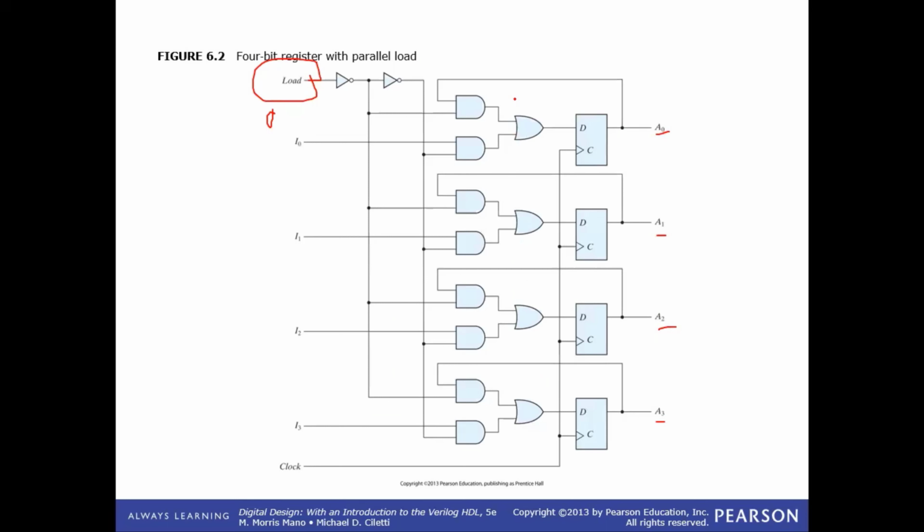Then we discussed that we do not play with the clock. We do not add gates to the clock because this adds delay to the circuit.